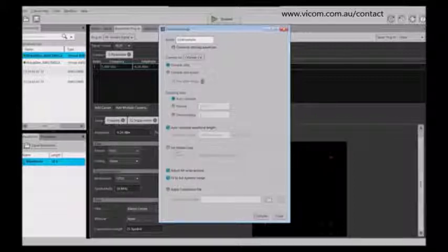You can also set marker data such that when you create a waveform, you can have a marker that's at the symbol rate, or for triggering or for other capabilities. So this gives you lots of flexibility on the markers. We automatically adjust for wraparound, and this is when you're repeating the waveforms, you want to make sure that each waveform is starting and stopping identically so that you don't have a spur at the beginning or end of the waveform.